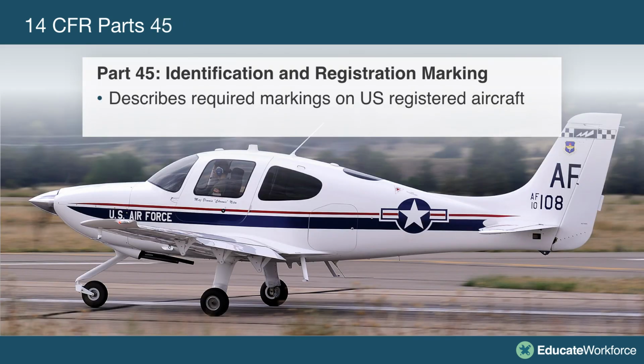(14 CFR Part 45) Identification and Registration Markings. Part 45 identifies the requirements for the identification of aircraft, engines, propellers, and certain replacement parts or modification parts. The nationality and registration marking required on U.S. registered aircraft. All certified products must have the following information on a fireproof data plate or similarly approved fireproof method. So first we need to have the builder's name, the model designation, the builder's serial number, the type certificate number if applicable, production certificate number if applicable.